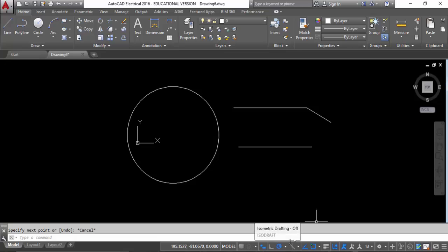Okay, the next little icon there is isometric drafting. So if you want to work on a 2D plane, draw up a 3D drawing on a 2D plane, you can draw an isometric. That'll allow you to do that, so it goes through to 30, 60 degrees. If you worked on the drawing board, it's quite nice when you've got isometric drawing there that you can use.